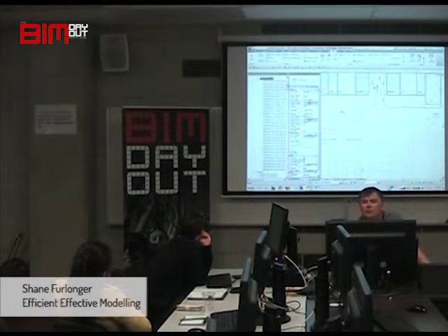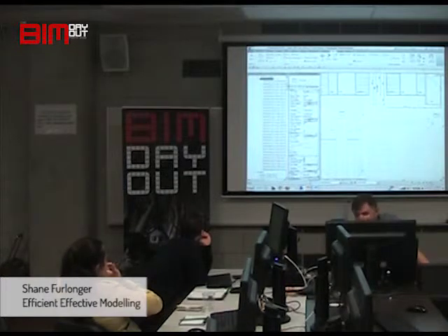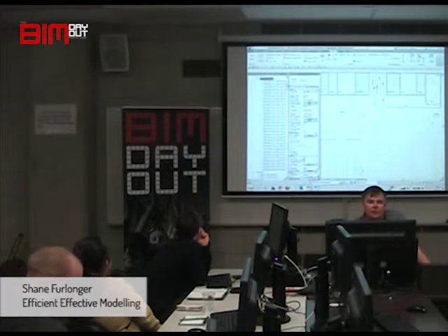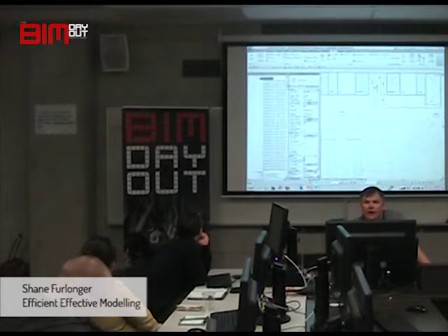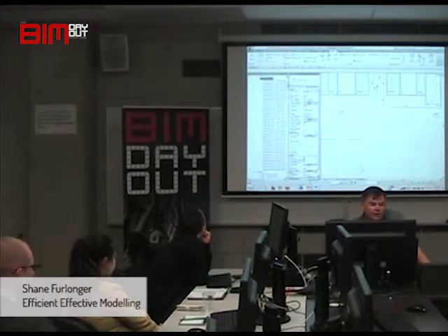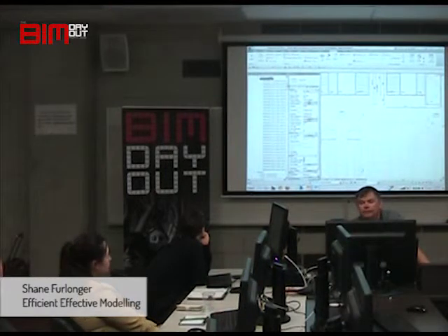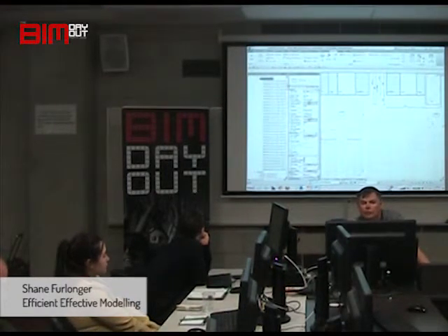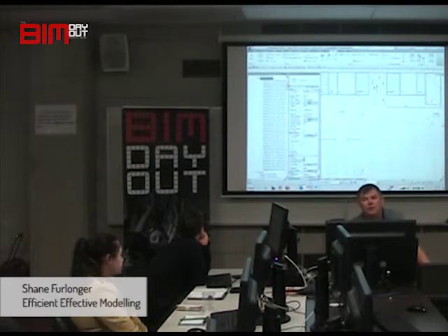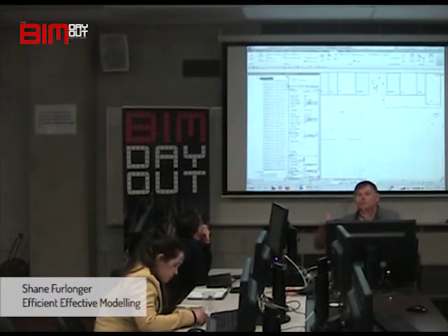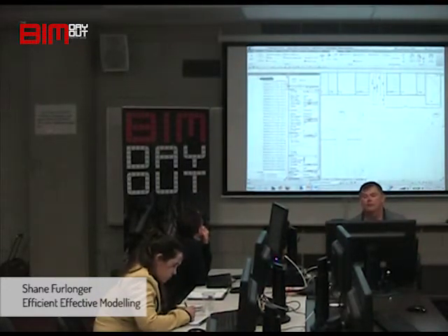And that's the only problem with doing legend views for walls and things like that, is you actually have to create more views for every sheet, because you can only drop one view on the sheet. But it's not a problem, you just create them as a dependent view, and then you only have to edit one thing. So when you edit your legend, you only edit it once, because the dependent view is of the same thing. It's not a dependent view of something else, it's of that exact thing.